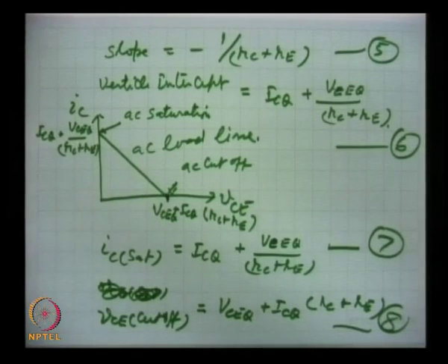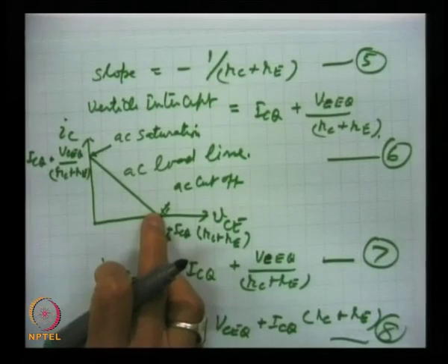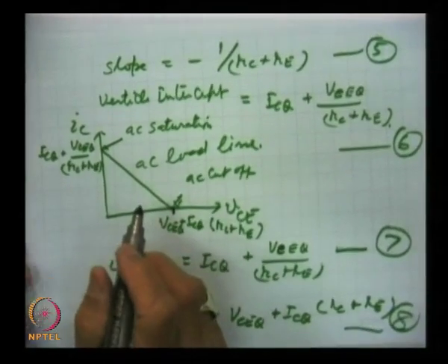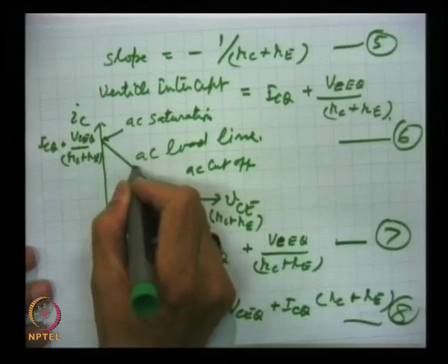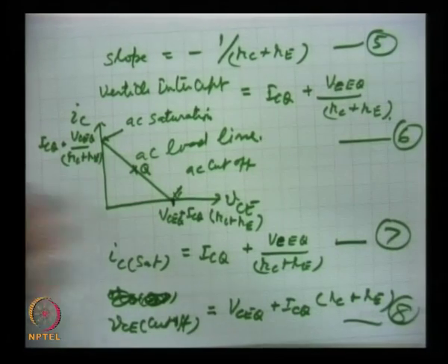The AC load line plays an important role when we plot it over the output characteristics of the power transistor. So we will be doing that, and then I will show you how to choose the operating point. Because the swing will be very large, almost the whole portion will be used, and hence it will be wise to choose the operating point somewhere in the middle for class A operation. This is what we do now.